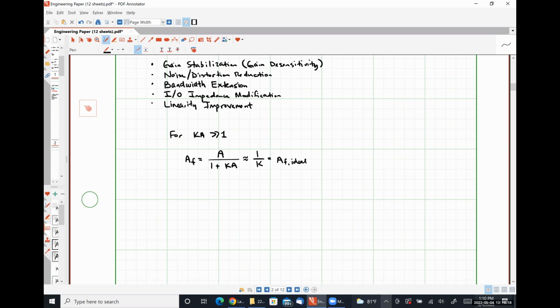Op-amp circuits, right? For a negative feedback op-amp circuit, our gain depends only on the resistors that we connect to the op-amp, not on the open loop gain of the op-amp at all, right? Or if it does, it's got a very, very small contribution when we're using the practical op-amp parts. Okay?